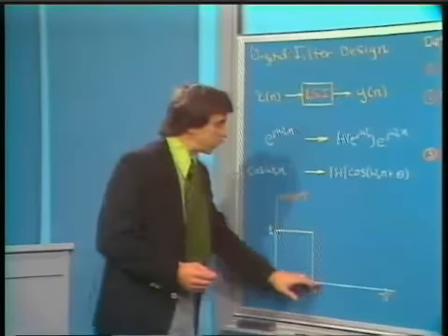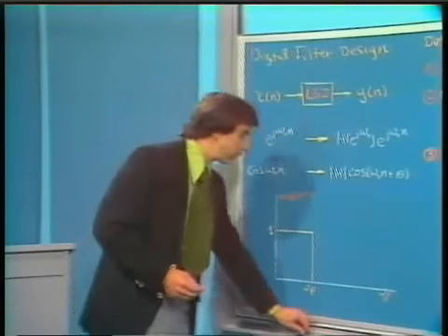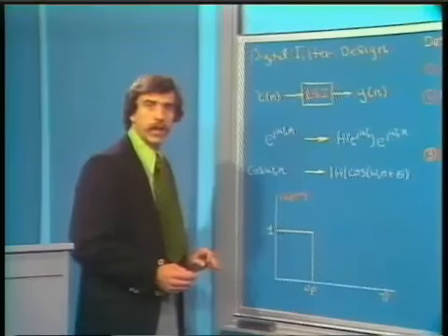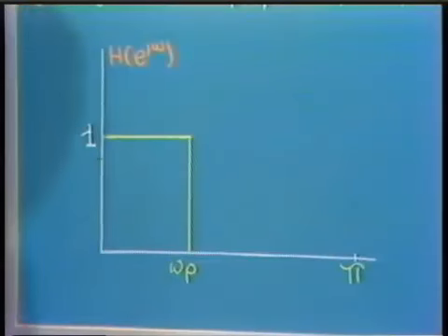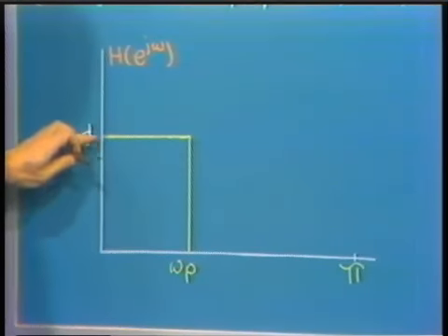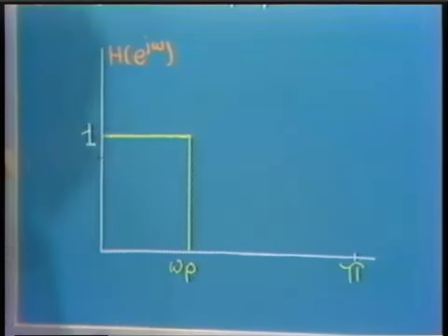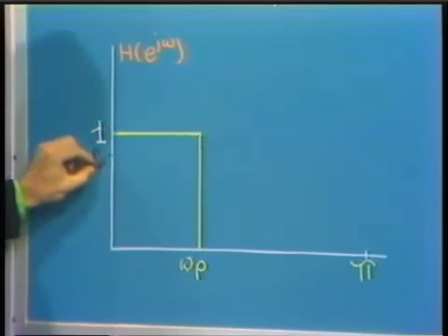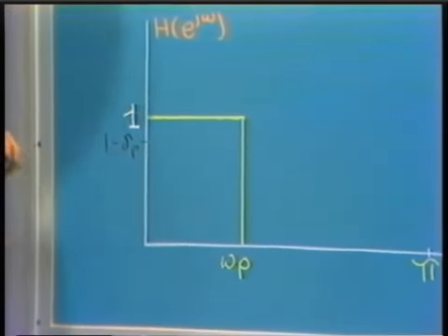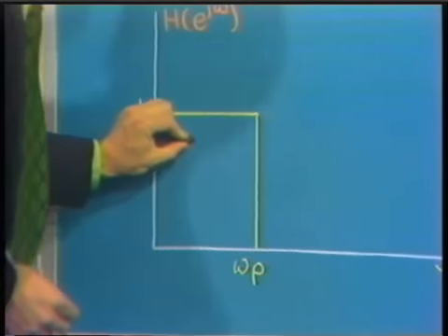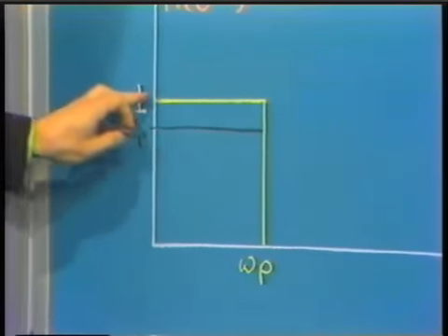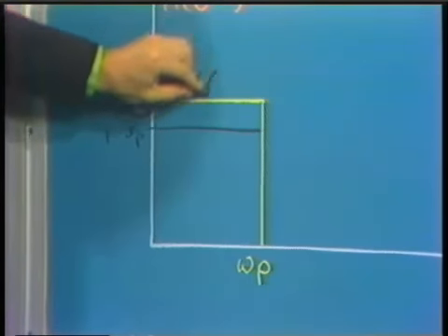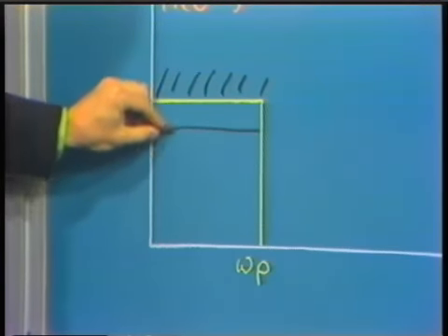So whereas we talk ideally about a filter characteristic as I've indicated here, in fact we have to allow some deviation from this ideal characteristic so that we would permit, as an example, a frequency response, rather than being unity in the passband, to deviate from unity by some amount, and let's designate that by, say, delta sub p, denoting a passband deviation, so that in fact what we might specify is a filter which in the passband, in the band of frequencies that we wish to pass, rather than being exactly unity, is constrained in the interval between unity and 1 minus delta sub p.